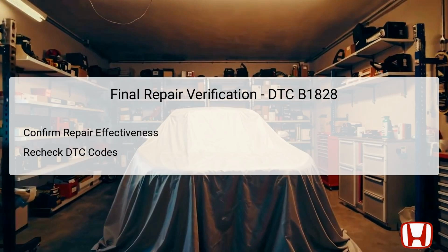Once repairs are completed, it is essential to conduct a final verification to ensure the problems have been effectively resolved. Start by confirming the effectiveness of the repairs performed, particularly focusing on the recline motor functionality and the overall power seat adjustment system. Use the HDS once more to recheck for any remaining DTCs, ensuring that the B1828 code is no longer present. Retesting the power seat adjustments in all directions is also advisable to confirm smooth operation and responsiveness.